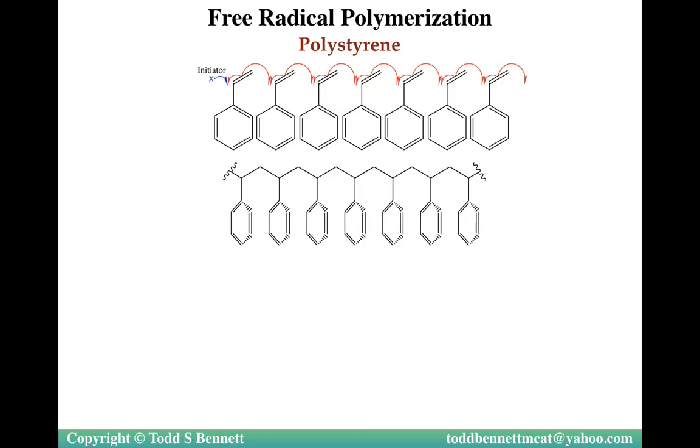You've also probably flown in a plane, or if not, you've at least seen a jet flying overhead going to the airport. The plastics they use, polystyrene, would not be very good for the windshield in the cockpit, certainly wouldn't be very good for the windows next to the passenger seats. So usually we use something like polycarbonate, a much stronger plastic, a harder plastic, and those are not necessarily made by free radical processes, but there are some. There's some plastics that are. So this can be an entire course, talking about how we design plastics, but for the free radical one, this is the basic gist behind it.